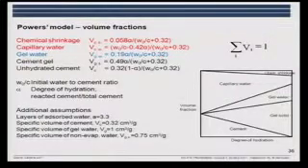And here you can see a schematic drawing of the volume fractions as a function of the degree of hydration, where you start out with having cement and capillary water, and then you will have the reaction giving gel solids and gel water, and decreasing the amount of the cement and the water.